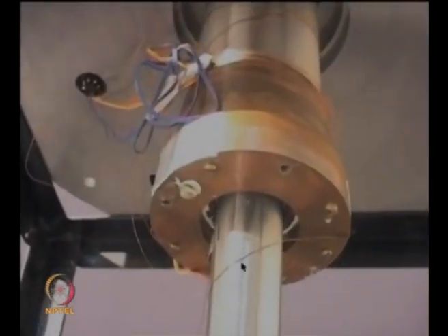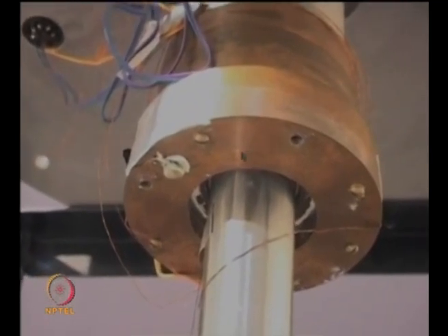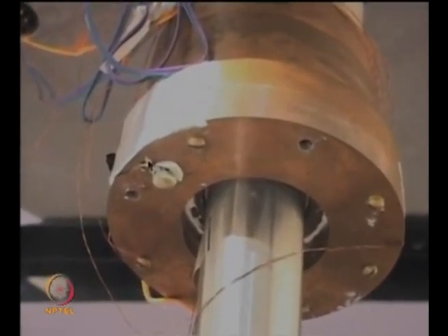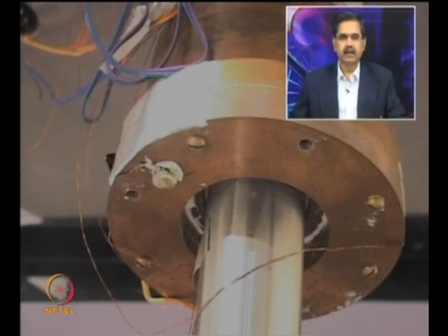This is the second stage, this is the first stage here, and what you see here also is a silicon diode which has been kept here to measure the temperature at this particular point. We can measure the first stage temperature at this point, and similarly we have one on the second stage. Now, you can see this flange over here which is copper. Anything I want to be cooled by the first stage can be connected to these different holes, or this could serve as a radiation shield for the second stage. One can put a radiation shield across the second stage. The entire thing has to go under vacuum, so that there is no 300 Kelvin radiation coming in, and you do not have air around this.